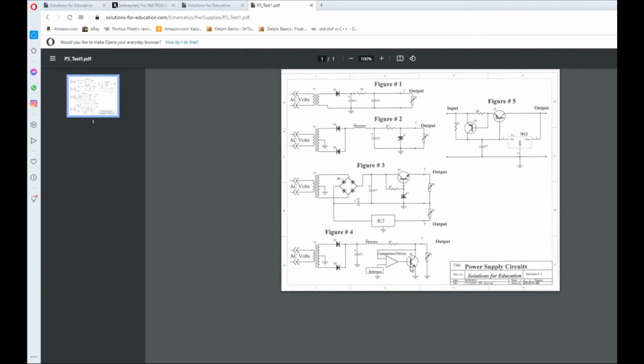But that's not true down here. Down here, you pull that load off, and if this transistor is not designed for that, it can say, oh me, oh my, this is more than you told me I was in this job for, and it'll pop that transistor because he has to take all the load since this guy here is gone. So this is the disadvantage of a shunt regulation system. The same thing would be true up here.